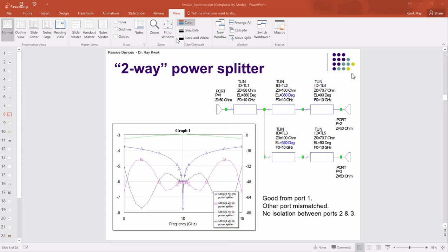Sometimes I see specs to like 25 dB, but anything beyond that is just noise. The reason is, as shown in this graph, this is the ideal circuit. You hardly get this. You have almost minus 80 dB return loss, right? This is just so unrealistic. I mean, with any mismatch, if you move the cable, this can jump up to 60 easily. This 20 dB, you can lose it easily.